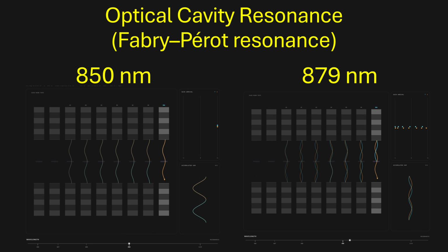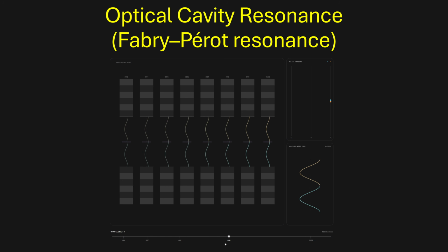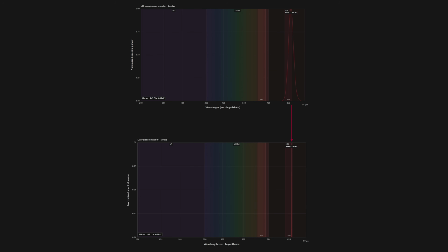You can already see the effect with only a few bounces, but if I show 1000 round trips, you can see that nearly every other frequency will not last long within the optical cavity. You can see that there are other integer factors that would resonate with this exact path length. However, these are not closely spaced because of the short vertical cavity, and they cannot be emitted by the gallium arsenide gain medium because its band gap produces a narrow gain region around 850 nanometers.